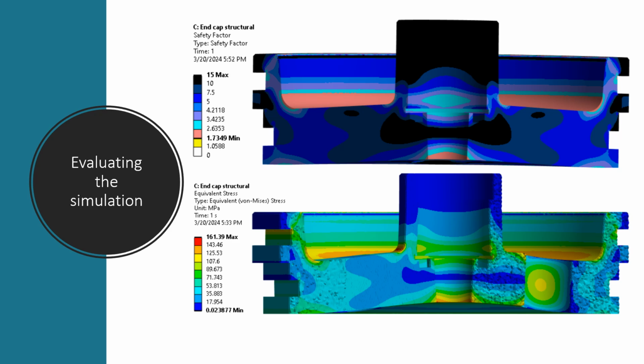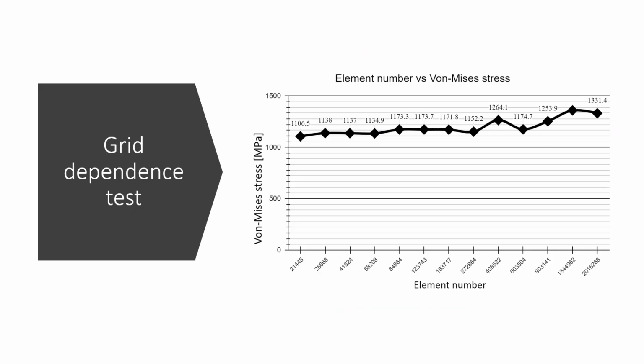And the reason for this is that it operates with huge matrices, and some solvers tend to ease up these matrix-based solvers by creating more iterations and not a direct approach. These are the two main solvers in Ansys static structural, the iterative based and the direct based. The direct, of course, can be much faster, but it needs a lot of resources, sometimes for big meshes. By big meshes, I usually mean above 1 million elements.